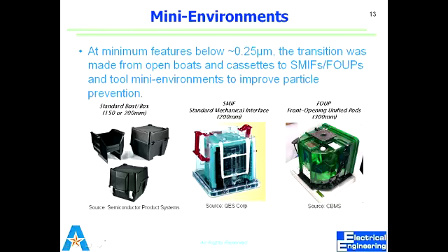Similarly for wafers, we always put them in a container. We never leave a wafer unattended unless it's in a box, closed tightly. We don't move a wafer by holding it in an open environment from one place to the other. We always put it in a container, close the container, and move the container. In industry, they don't work on one wafer at a time. They have big cassettes with multiple wafers, and the whole cassette is moved from one place to the other. Every module has a receptacle that captures the cassette and then takes one wafer out at a time, or whatever the case may be.